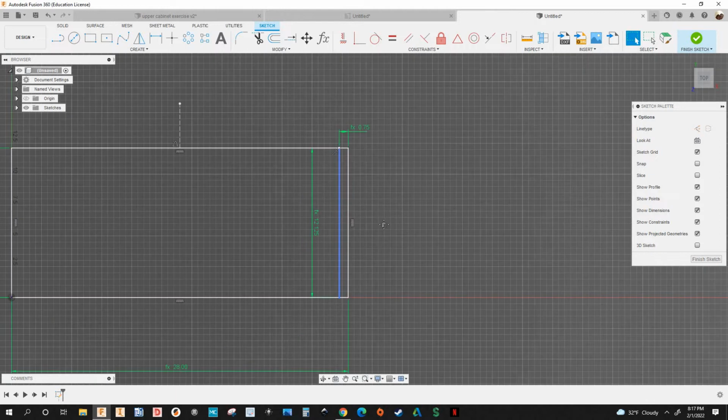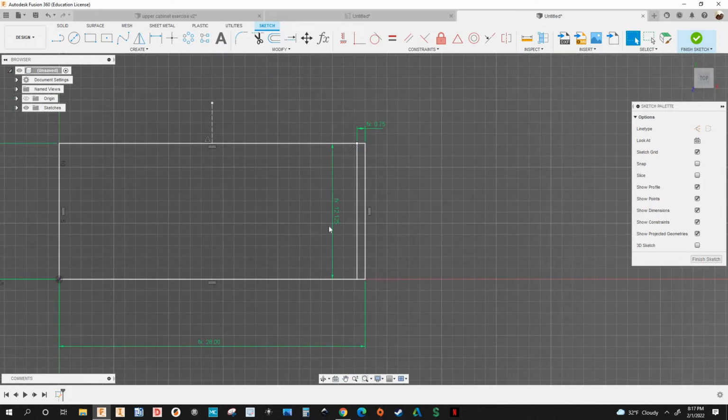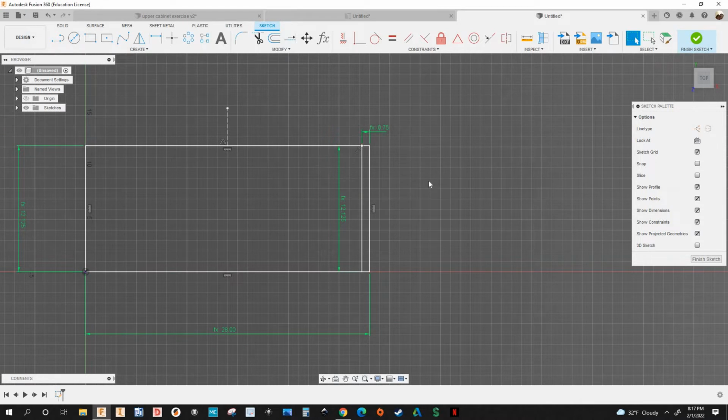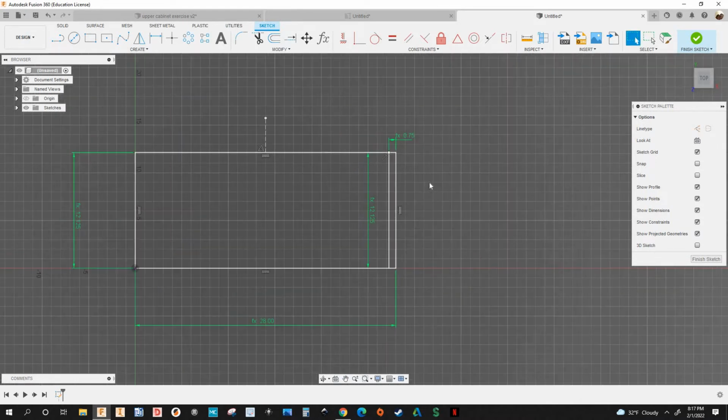Okay, so I'm gonna mirror this line. So I'm gonna go up here. It says mirror. Okay, you can use the design shortcut. All right, so you can hit S. You bring this sketch shortcuts window right here. And you can type mirror. Okay, you have two different types of mirror. This is the sketch, and this is 3D modeling. Okay, so you're gonna select this one right here.